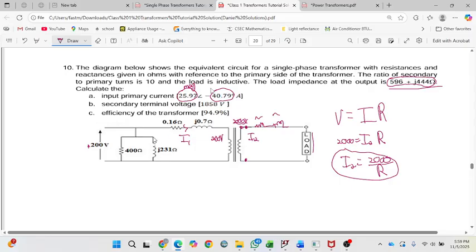And then clearly from here, you all could see that you could calculate your I no load. Really easy because we literally did it in the previous question. 200 divided by 400, and then this divided by that, you'll get your I no load. And remember, your I in is basically your I no load plus your I1. If you had just said I1 and that was the answer, you'd get it wrong because, as I said, the input current is your no load current plus your I1 current. So just be careful how you're doing this stuff.